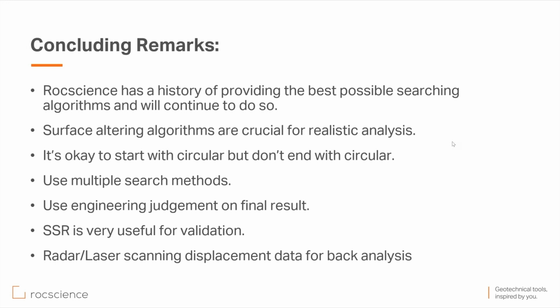Okay. My next is use multiple search methods. One of the questions that we always get is, I use this method, I'm getting a different factor of safety than this method. And my answer is, there are a lot of searching methods in Slide. And believe me, if there was one method that always worked for all possible situations, we would only have one method. But that is not the case.